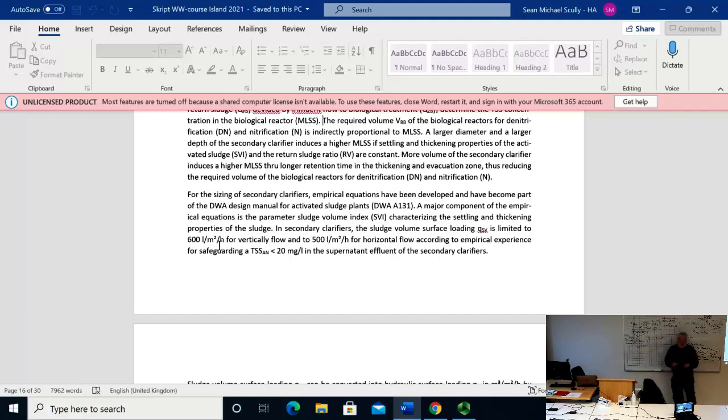When you now know the required surface area, you know how much PE you have connected to your treatment plant, because you know the inflow load and capacity. The 91 is also because we have 100 liters per day and PE.